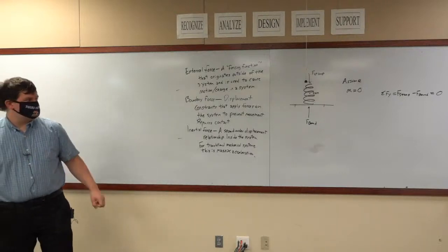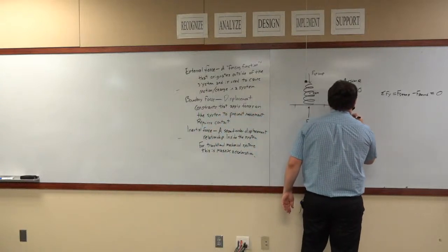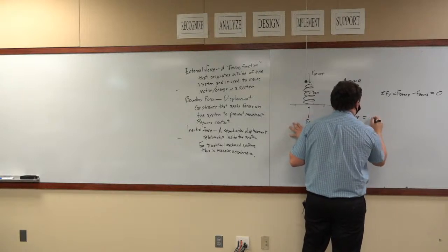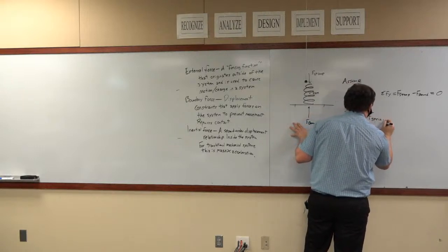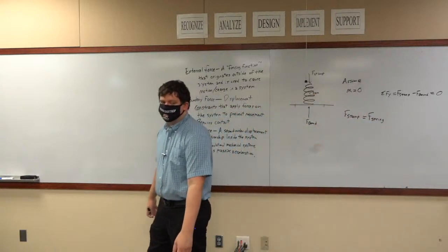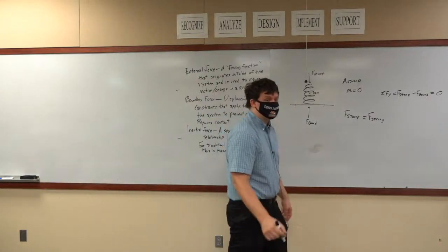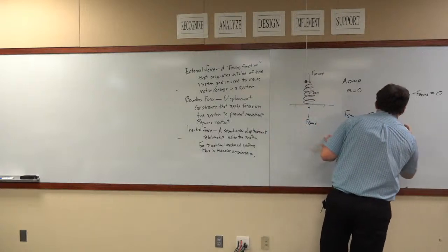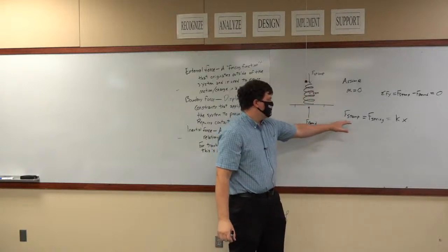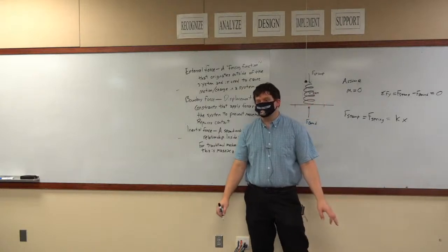You can figure out how much this compression is based on, you know, that F stamp is compressing the spring, and that spring force is going to be equal to F spring. And your spring force, anybody remember the relationship for spring? Times X, yes. It's equal to, well, I'm just going to put positive Kx. Okay? So the stamping force is directly related to the displacement of that spring now.